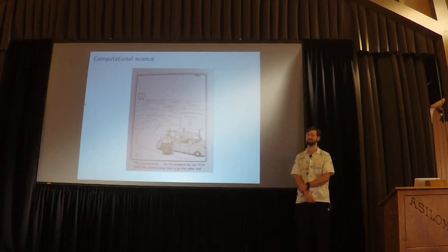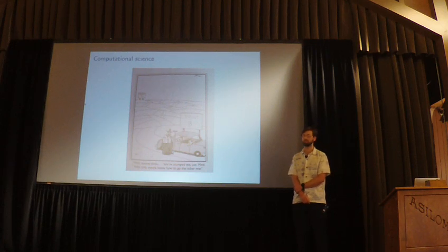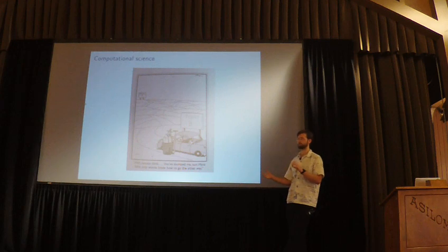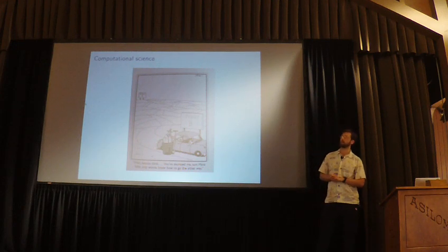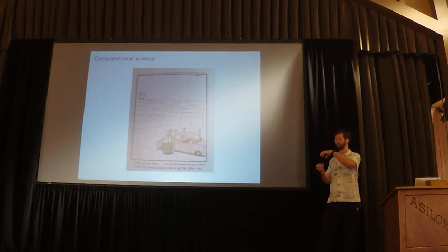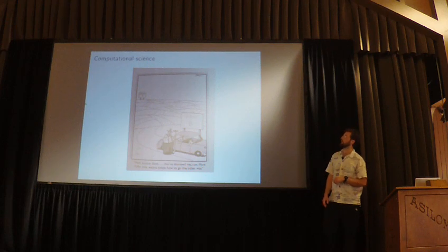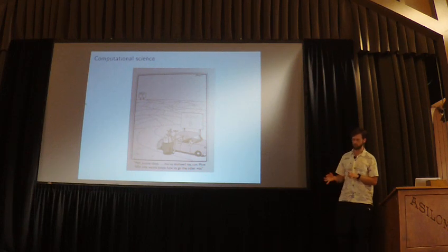Thanks. The first question I have is, have you done comparison with some standard tests, such as Coulomb tests with your C11 and C44? Right, those are standard testing in the industry. The answer is yes. It's limited, we've done limited tests with these conventional ones. I'm not the material scientist here, but you're talking about just loading a dog bone at 2 ends and pulling it. Right. Yeah. So we did that for a CMSX4 sample, and everything lined up pretty well.